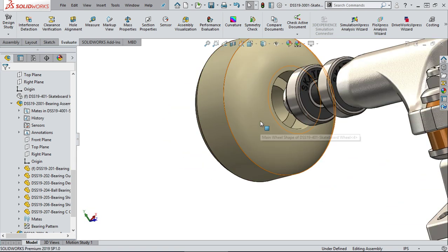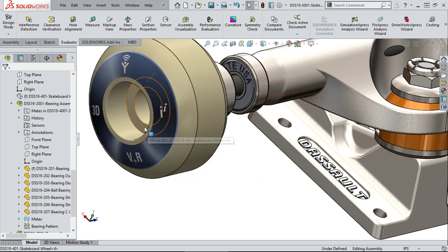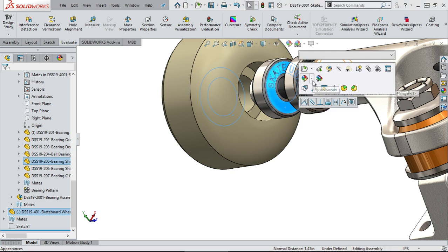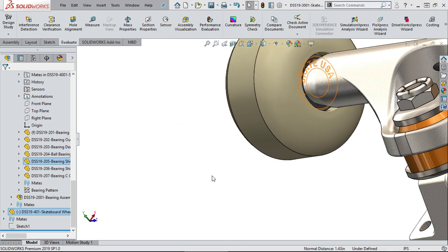And of course, if you happen to miss that dialog box, if I pick one, hold Control, pick the other, let go of Control, and then I move away, well, now we know you can just tap the Control key and bring that box back. So you don't have to hit escape and start all over again.